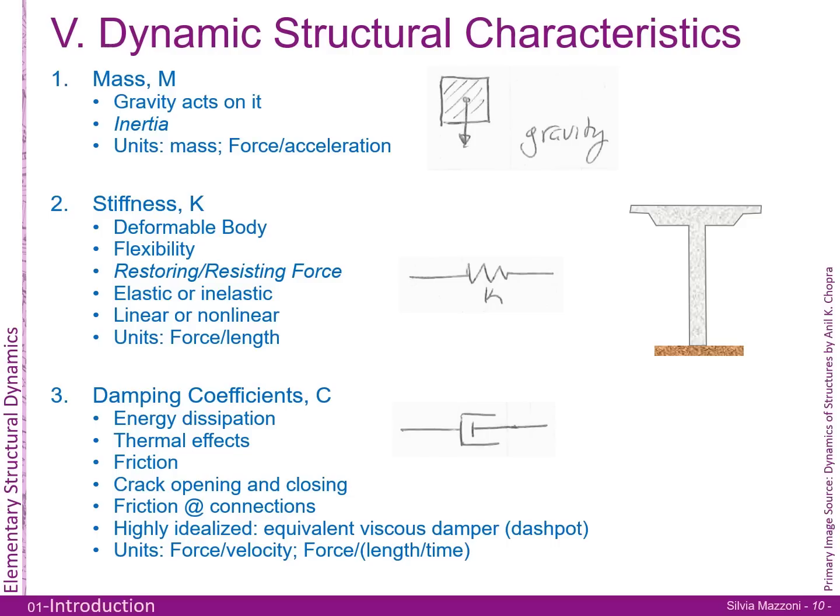As I've talked about before, damping is the main term in energy dissipation. What you keep in mind is inelastic systems can be represented by elastic systems, just put in more damping. Which means that if you're modeling your system with inelastic models, make sure you bring your damping down, because you're modeling it hysteretically, reduce the overall system damping. So maybe instead of doing 5% when you're doing nonlinear analysis of strong structures, you actually go to 2% damping.